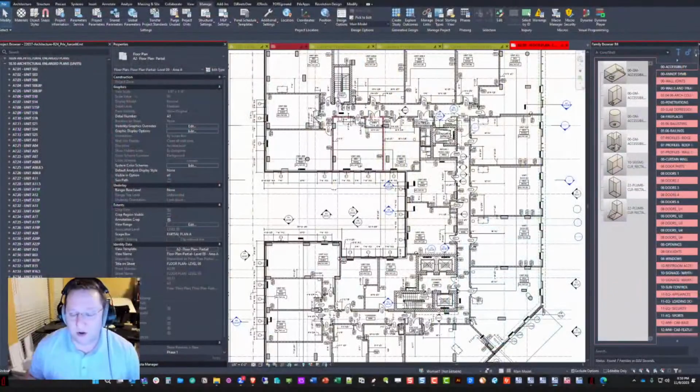Yeah. And something that we always talk to consultants about is there's a whole bunch of things that us BIM folks love to write documents telling consultants how to do. And I don't know, a bunch of you in the chat may have this. Who has an email that's really convoluted that explains to their consultants how to load in their shared parameters to fix their drawing list? If you just copy the drawing list out of the architecture model, it automatically does all the shared parameters for you. No one should ever load a shared parameter manually. Just copy it from somebody who's already done it.